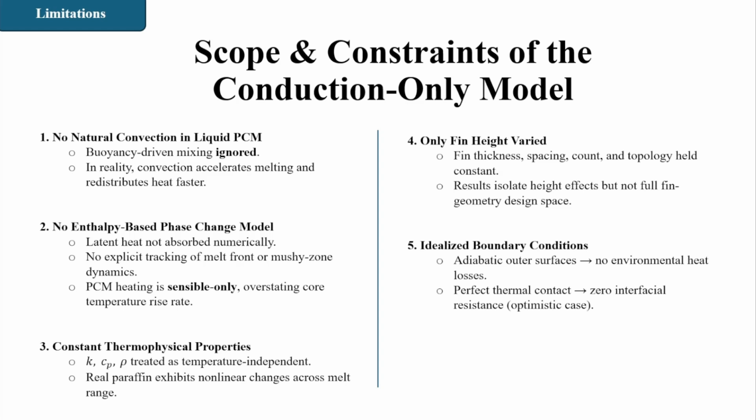A couple of things here is that the results reflect conduction only. They do not include convection inside the melted PCM, latent heat absorption, temperature-dependent material properties, or realistic heat loss conditions, which are a couple of limitations that the project has. Also, the fin height is the only variable, so the study doesn't explore full fin topology, as it could be better. The model is intentionally simplified to create a baseline before adding more complex melting physics, essentially.